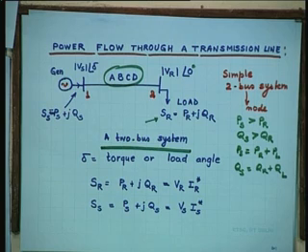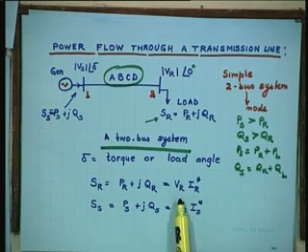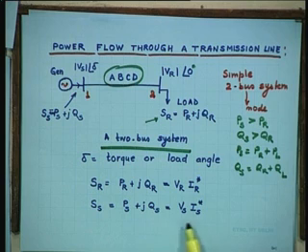Delta is a very important parameter, it is called torque angle or load angle. We have already talked about delta earlier on. In fact, we have drawn a phasor diagram also, if you recall chapter 4, the salient pole synchronous machine and non salient pole, that is cylindrical rotor machine and so on. SR is PR plus JQR is equal to VR IR star, SS is PS plus JQS is equal to VS into IS star. Star is conjugate.